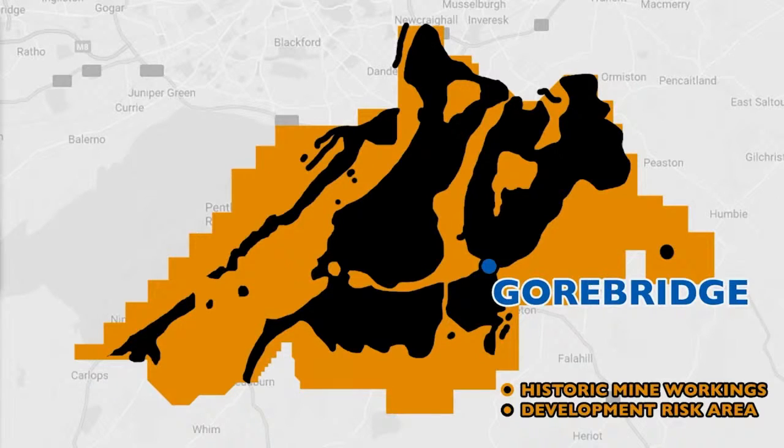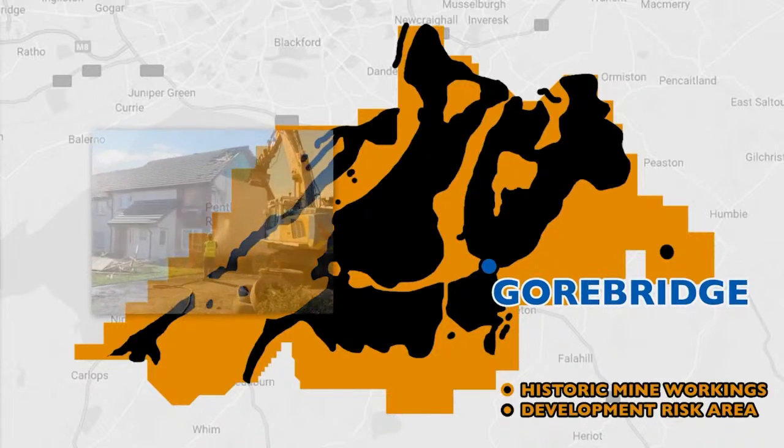However, when housing was built on the site, incorrect foundations were used, and this, combined with construction of a nearby railway line, disturbed the ground and released high volumes of gas from the mine workings. It's also possible that the investigation boreholes themselves may have contributed to the release of gas from the mines. Combined with a period of exceptionally low atmospheric pressure, this CO2 entered several properties on the site, causing various health problems for residents. In some properties, concentrations of up to 20% have subsequently been detected.